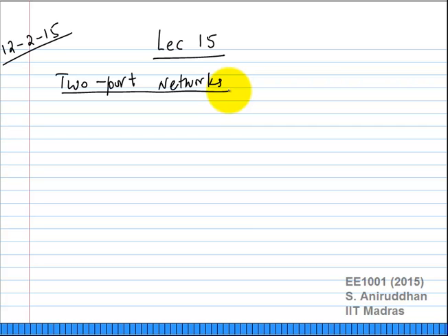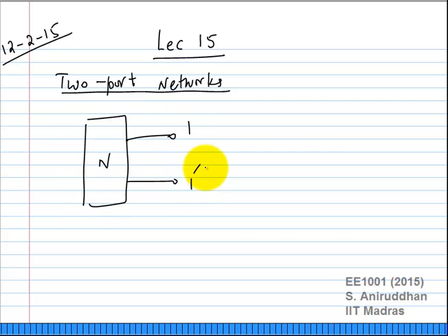And then we made more complex interconnections out of these, and just a couple of classes ago we found out how to represent complex networks across one pair of terminals, right? We took any network N and learned how you can replace it, if this network contains resistors, independent voltage and current sources, and control sources as well.